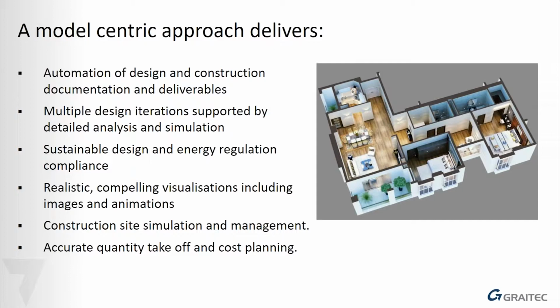So this idea of a model-centric approach, automatic design and construction documentation: basically what happens is, as you draw, all the information is being generated as you draw. So for instance, if I draw a floor plan and I put my windows in, my elevations are being generated automatically. So I don't have to draw them separately, because I'm drawing a three-dimensional model. Even though I might be in a floor plan, there are still heights to my walls, there are still offset heights to the windows, we've got head heights on doors, etc. That means that when I go to an elevation, it's already been generated.